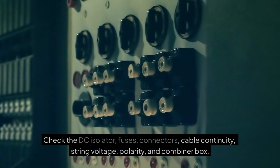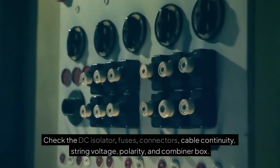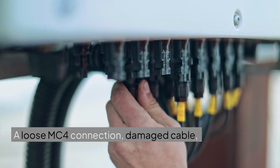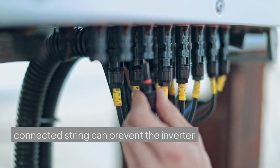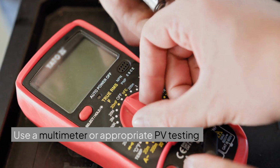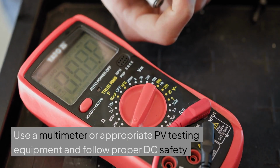Check the DC isolator, fuses, connectors, cable continuity, string voltage, polarity, and combiner box. A loose MC4 connection, damaged cable, blown fuse, open isolator, or incorrectly connected string can prevent the inverter from receiving the expected PV voltage. Use a multimeter or appropriate PV testing equipment and follow proper DC safety procedures.